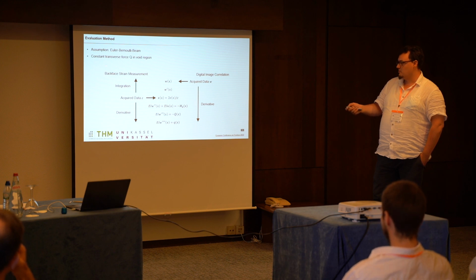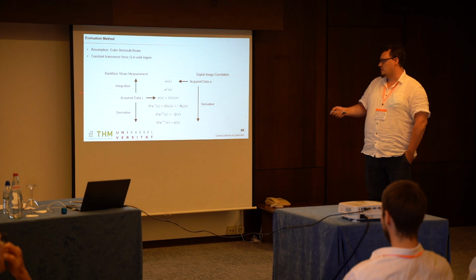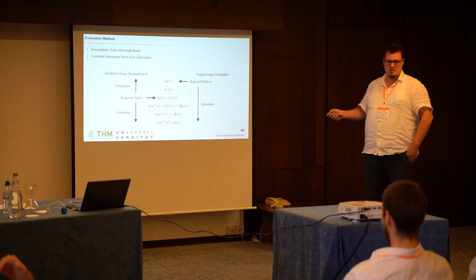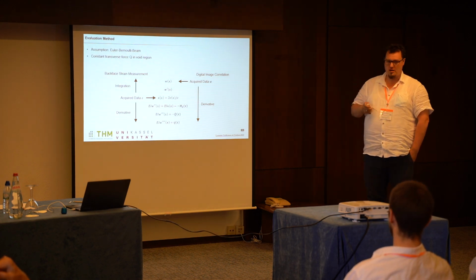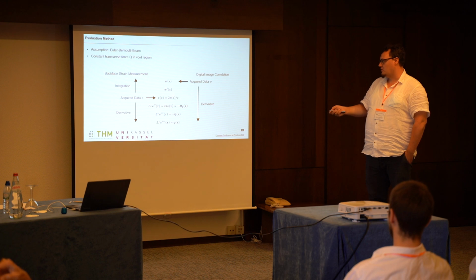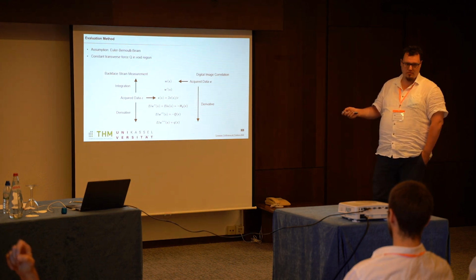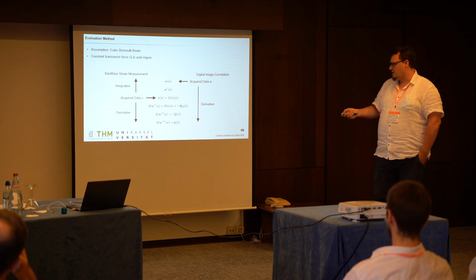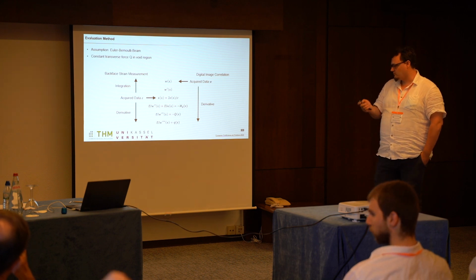The backface strain measurement is easier. Our acquired data is epsilon, the fiber strain, and with the distance from the neutral axis to the marginal fiber, c, we can calculate the curvature, and the curvature is proportional to the bending moment. We have to differentiate this once and get the transverse force.